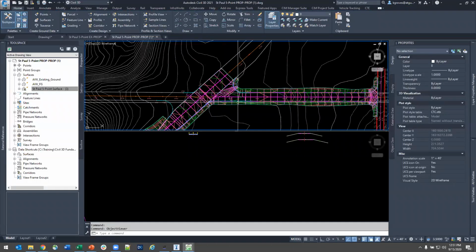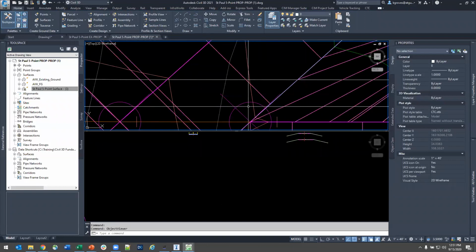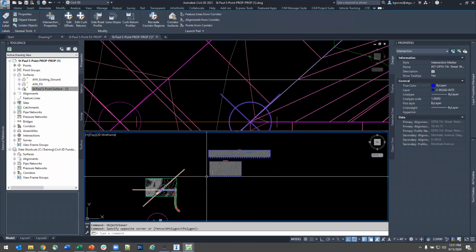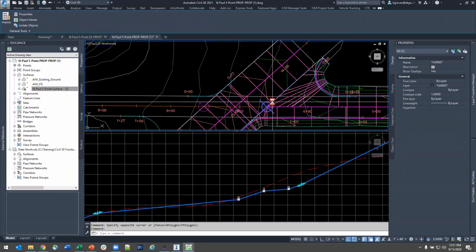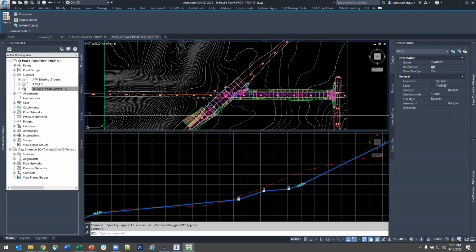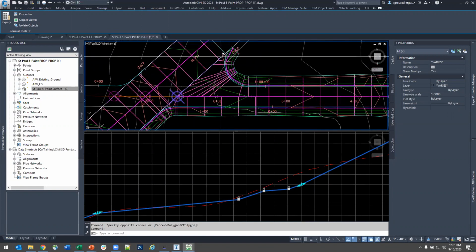So that's what we're doing here, folks. We're going to be using the intersection wizard. My recommendation is simply for the profile locking capability. And then from there, you're going to create your own custom connected alignments, manage those stations so that you only have the one assembly to use for it, and then put it all together.